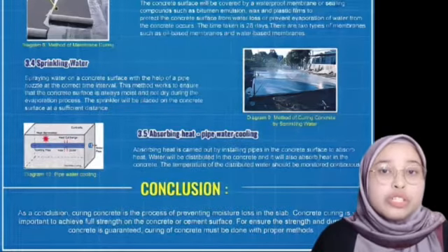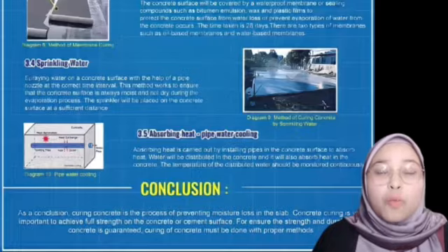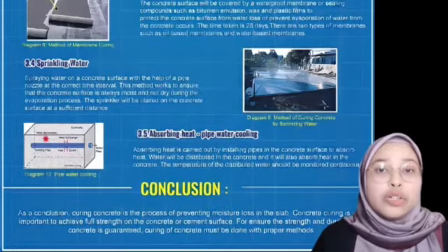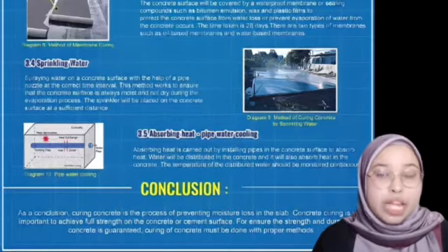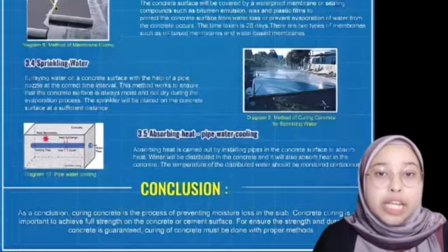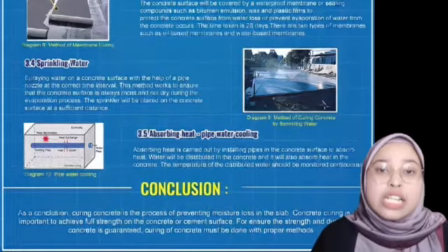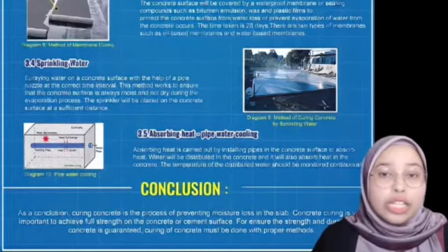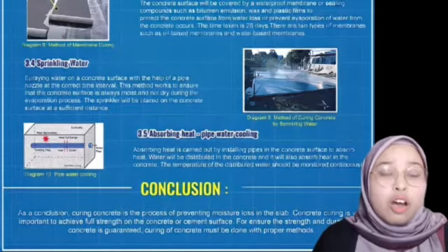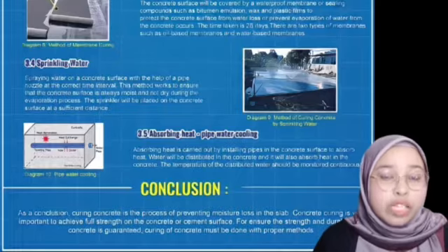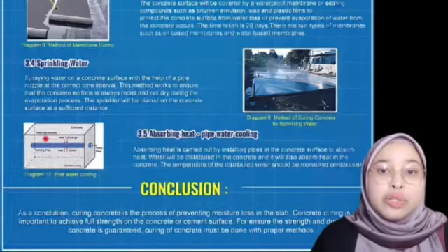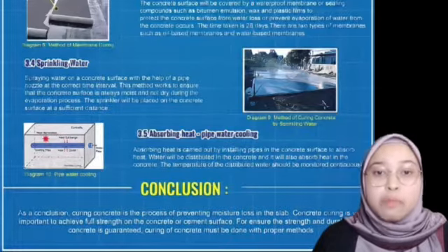Curing of concrete should begin as soon as the formwork is removed after the initial setting time, and must continue for a reasonable period. There are several importances of curing concrete in construction, such as maintaining mixing water in concrete during the early hardening process, preventing the loss of moisture from the surface of the concrete, and accelerating strength gain using heat and additional moisture.